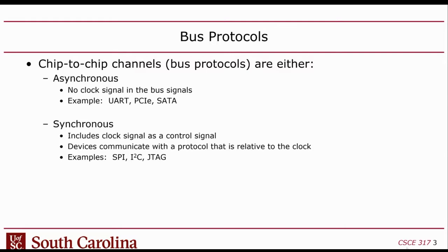Now you might say, why in the world would you want to send more bits than you need to? You do that so you can maximize the number of transitions in the link. That way, if you just happen to send a bunch of zeros, they don't come across as a bunch of zeros. They come across with a bunch of transitions in there because it's encoded. And that way, you can design an analog circuit called a phase lock loop that will recover the clock signal from the data signal. So basically the clock becomes embedded in the data signal.